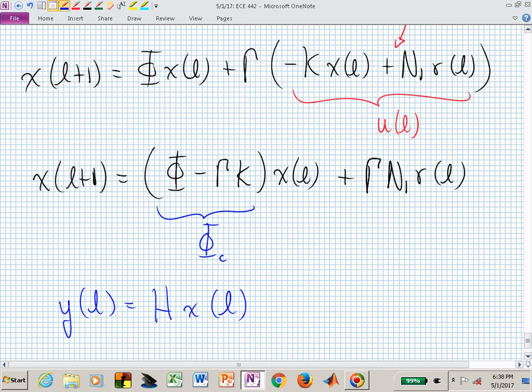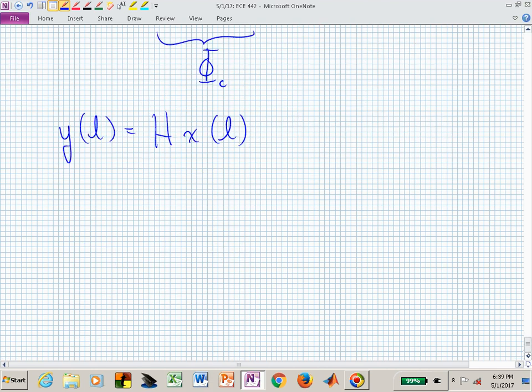And what we just said is let's find the transfer function between little r and the output and set that transfer function to have a DC gain of 1. So we're going to find this transfer function as a function of z. And what value of z do we use if we want to look at it at DC? Again, 1. At z equal to 1, right there on the z-plane. So let's now find our transfer function.